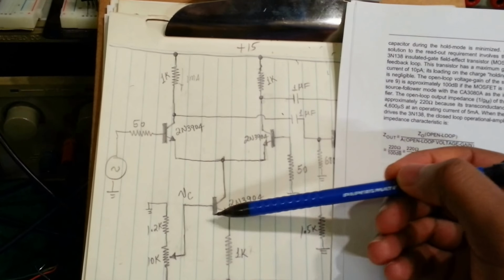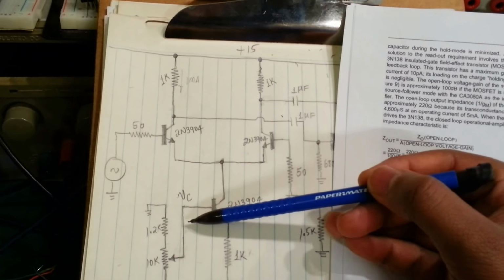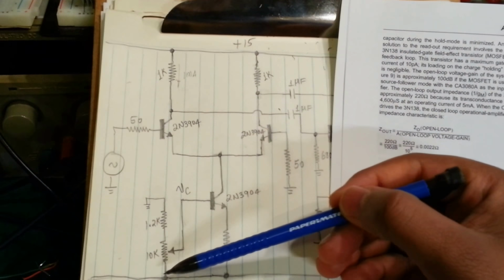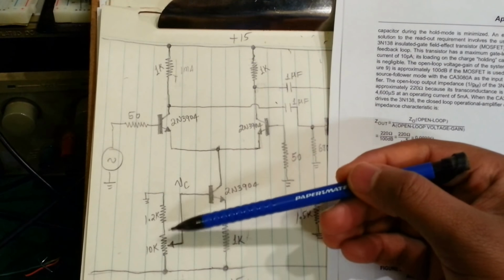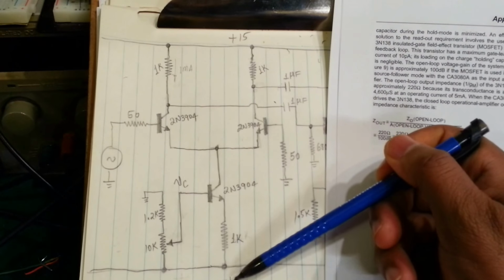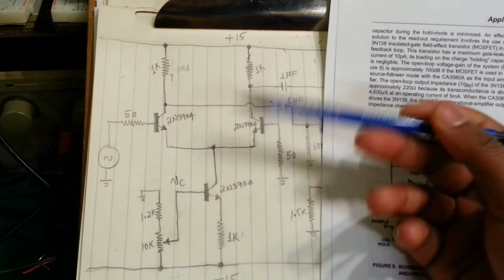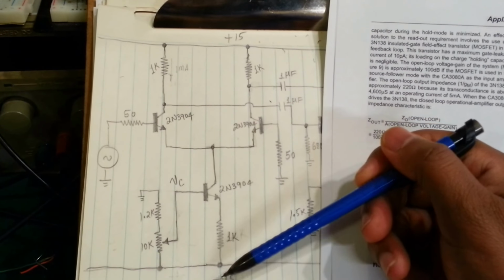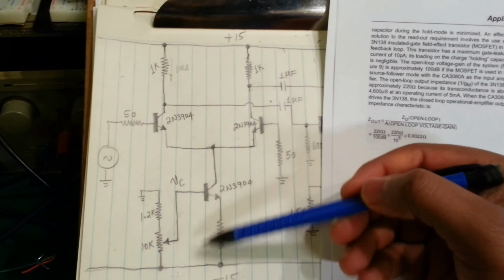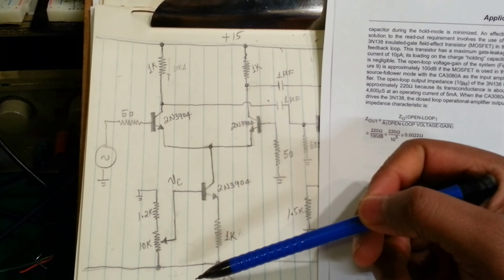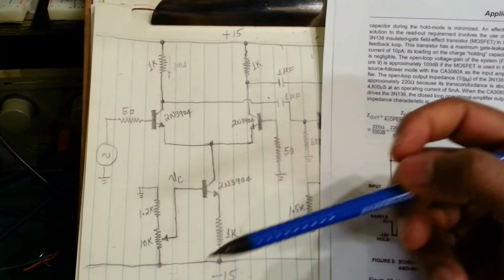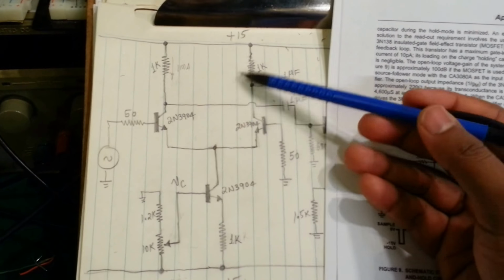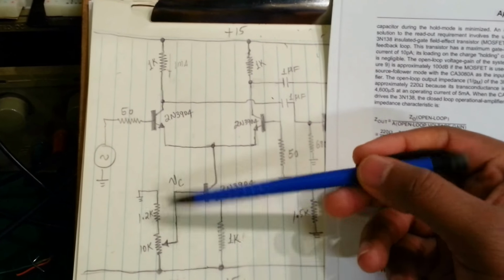The book suggests using a second DC source here instead of deriving this controlling voltage from the existing plus or minus 15 volt power supply. But usually in circuit design, you're always trying to minimize the use of power supplies, so I have designed it this way.